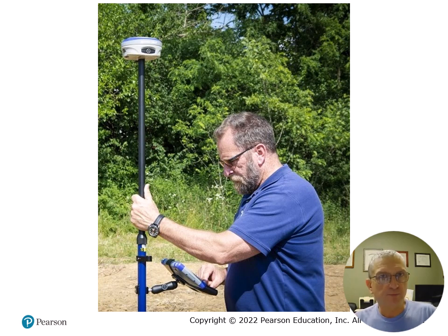And even after it's built, in order to get title insurance and to get commercial lending and funding from banks and investors, properties are going to have to usually have ALTA NSPS land title surveys. Even if they don't require ALTA surveys, at some point they're going to have a survey to delineate and demarcate and define what's being sold.